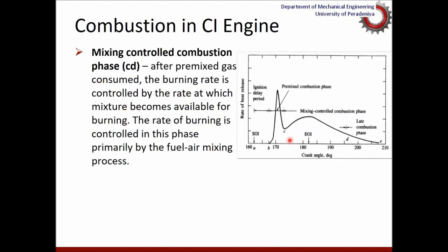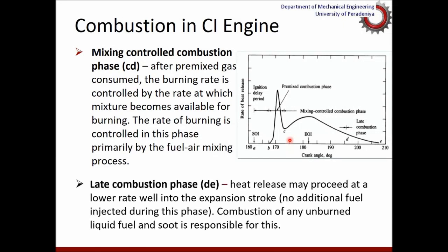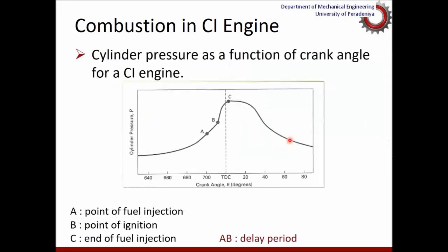Then comes the mixing controlled combustion, where the burning rate, as I said earlier, decides how the mixing takes place for combustion. And then late burning, the last part of the combustion, and that is how diesel is burnt in internal combustion engines.